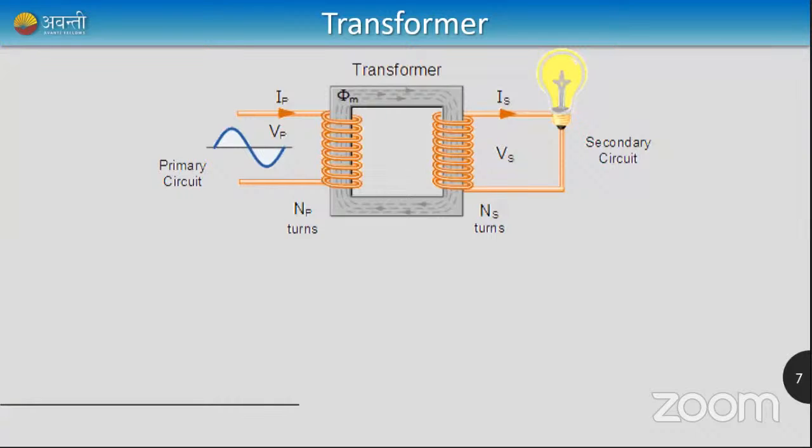Okay, so coming back to the chapter now. We'll discuss how it works and what the principle of transformers is. Let me write two, three points which are very important. Transmission is difficult because of high current. If current is high, dissipation, heat loss, is also high. So I use transformers to reduce current. Then I can transfer it very easily. When current is low, transferring is very easy.